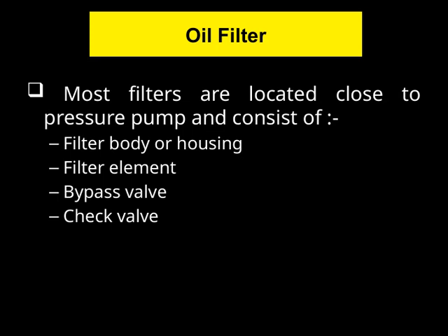Most filters are typically located close to the pressure pump, which makes sense because that's where the oil or hydraulic fluid is under the highest pressure and most susceptible to contaminants. When we look at the components of these filters, you'll notice they usually consist of a filter body or housing, which is the main casing that holds everything together. Inside, there's the filter element itself. This is the part responsible for trapping dirt, debris, and other particles to keep the fluid clean.